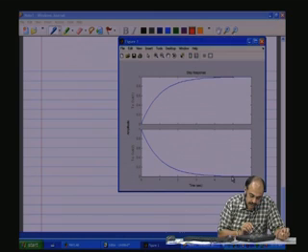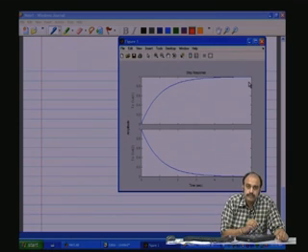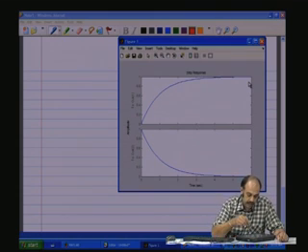Now, notice that there are some interesting features here. In the voltage across Vc, you see that the output is growing and settles down at 1. The input is a unit step. It is growing and settles down at this particular value 1 here. Now, in the case of Vr, it is decaying and settles down at around 0, or exponentially it decays to 0.